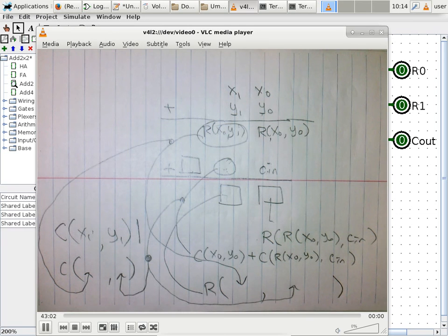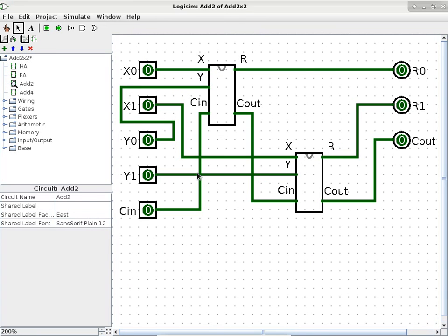Okay, so at this point, we have about 5 minutes left. So what I want to do is to relate what you're doing with the main point of this whole thing. If you look at the design that I did, which is this one here, this whole thing is sequential. In other words, the most significant bits won't settle until the least significant bits are done computing. One particular bit has to propagate in a very sequential manner, which is the carry bit.